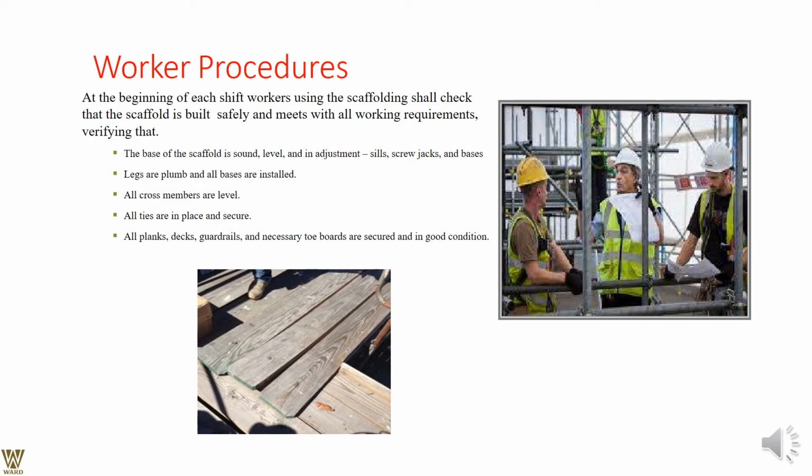The base of the scaffold is sound, absolutely level and in adjustment. Legs are plumb and all bases are installed. Cross panel members are level. All ties are in place and secure, and all planks, decks, guardrails and necessary items are secured and in good condition.